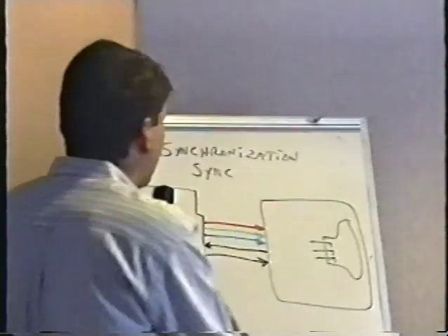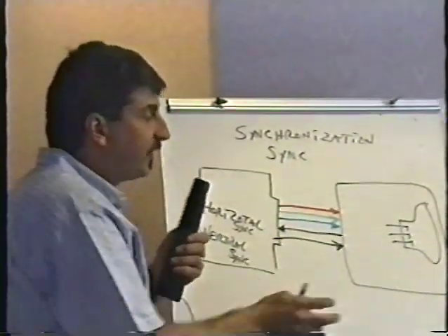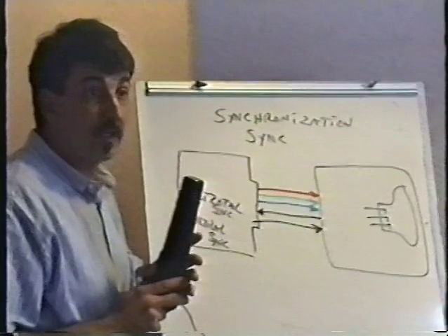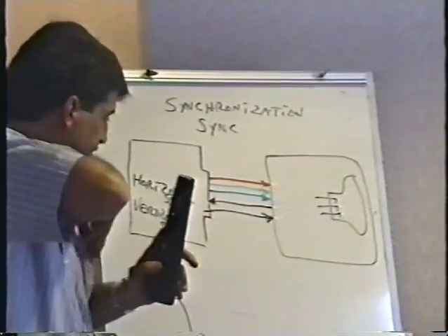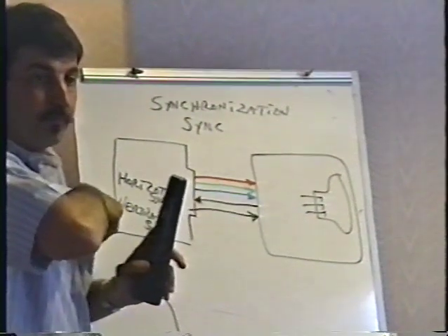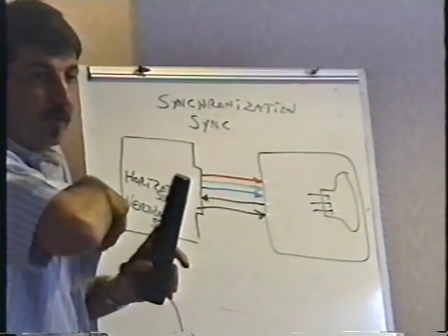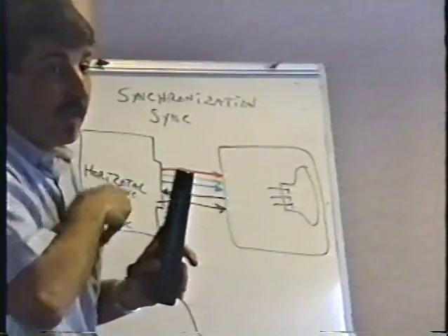So when you think sync, think to yourself, is the thing rolling vertically? I have a vertical sync problem. Is it shifting left and right? I have a horizontal sync problem. Okay? Make sense? So to fix something like that, you would first go to the vertical or horizontal holds? Yes. And then after that, yes.